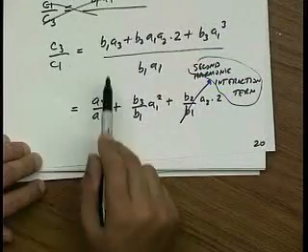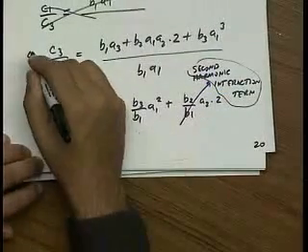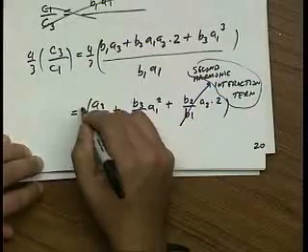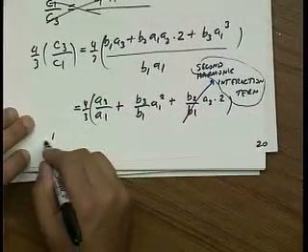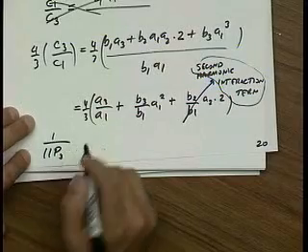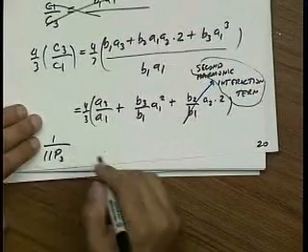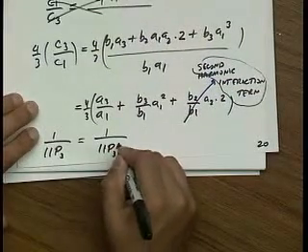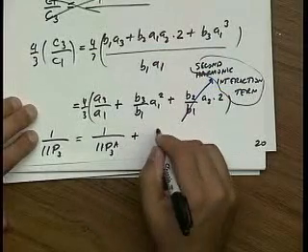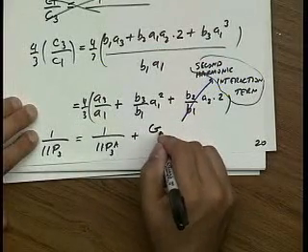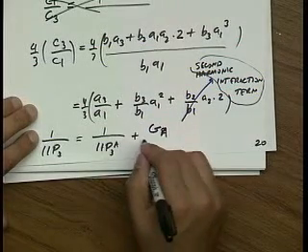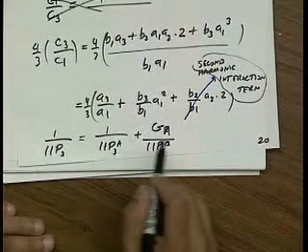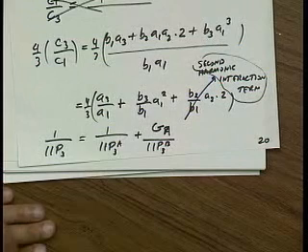If I just multiply this equation by a constant 4/3, so I multiply here by 4/3, here by 4/3, and here by 4/3, I can write this as 1 over the input IP3 of the overall amplifier, the cascade, is equal to 1 over the input IP3 of amplifier A, that's this term, plus power gain of amplifier A, input IP3 of amplifier B. Okay? This is the power gain because it's the voltage gain squared.